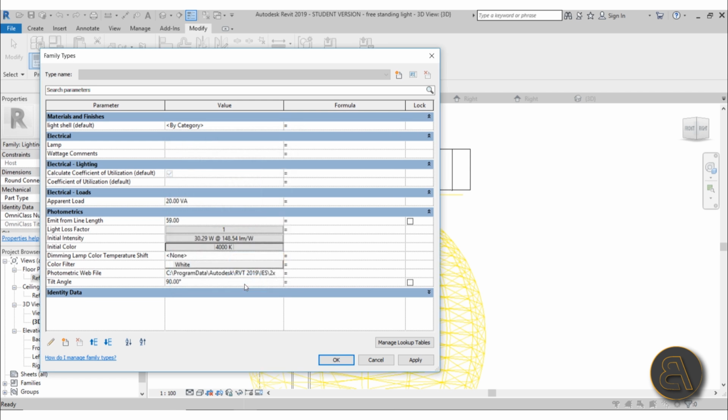Most of the lights I modeled so far were 4000. I did mostly LED lighting for offices, stuff like that. So in those cases you're going to go with 4000 or above to get more of that white light. And if you're doing something for residential buildings, for maybe a living room or a bedroom, you would probably go with a more yellowish light, just because it's more comfortable in those types of environments.